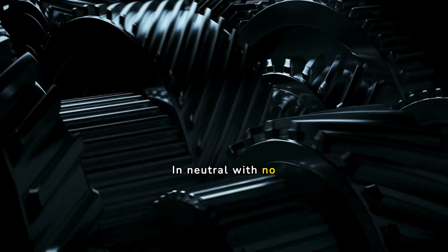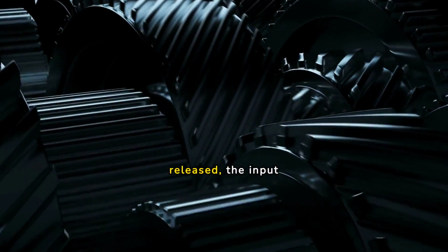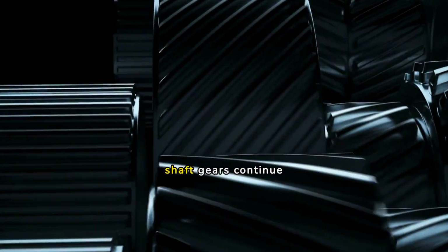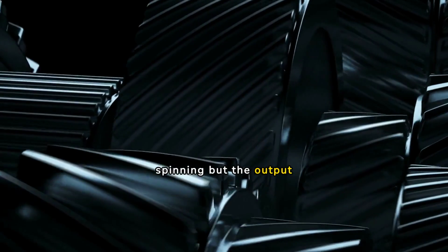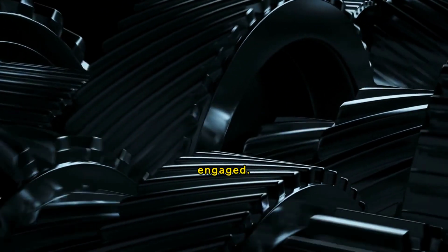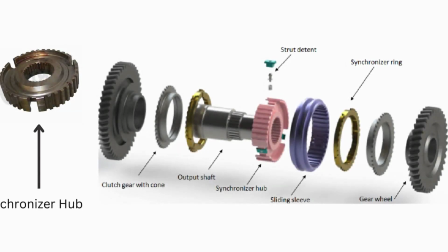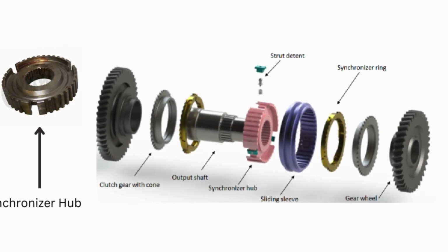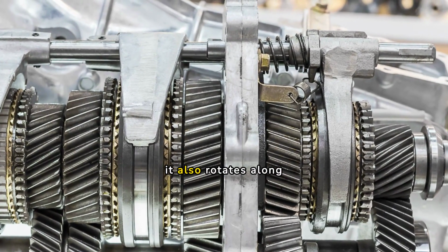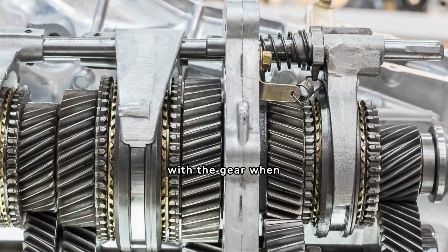In neutral with no gear selected and the clutch released, the input shaft, the counter shaft, and the output shaft gears continue spinning, but the output shaft does not move because none of the locking collars are engaged. Along with the locking collar are the spline sections mounted on the output shaft parallel to the locking collar. The synchronizer hub is fitted over the spline sections. The splines lock the synchronizer hub so that it also rotates along with the gear when engaged.